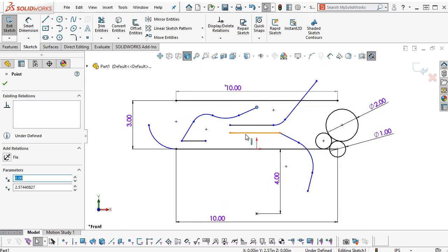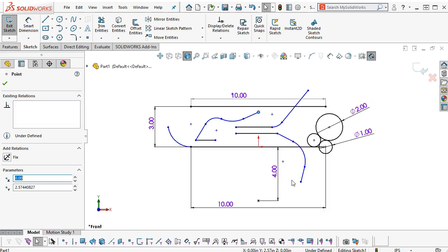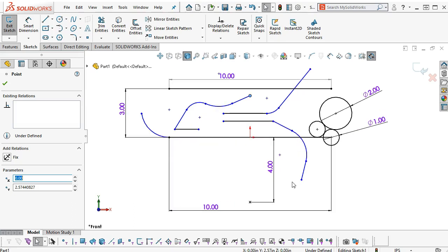All right, so just like here where it's coming off, we haven't set an angle, but my pencil is taking a change in direction. Those lines aren't collinear. It doesn't make a 90 degree, so it's not perpendicular. We need some additional dimension or some additional item to cause this to go fully defined. All right, so I know I've thrown a lot out there.